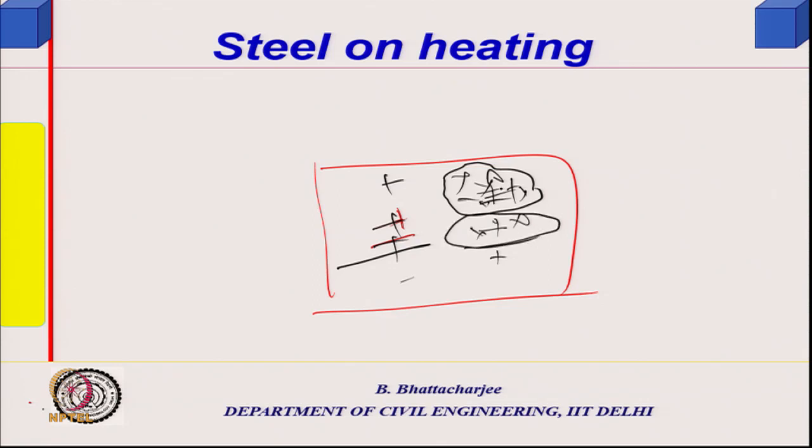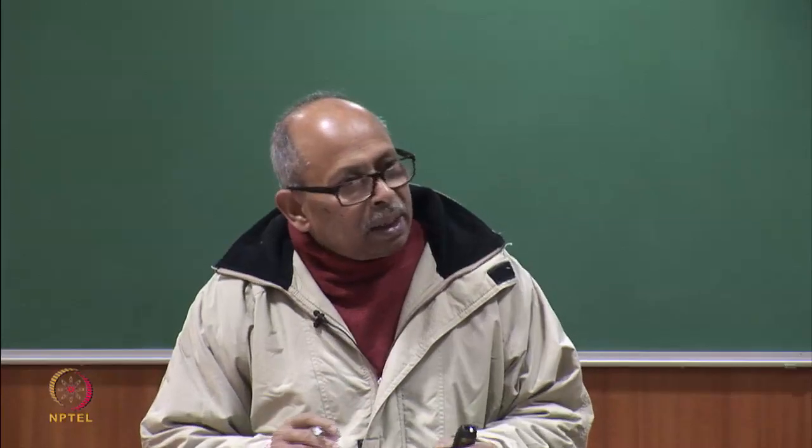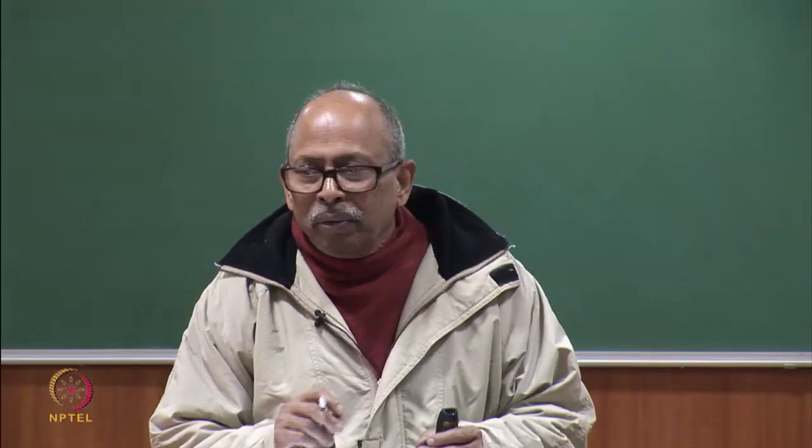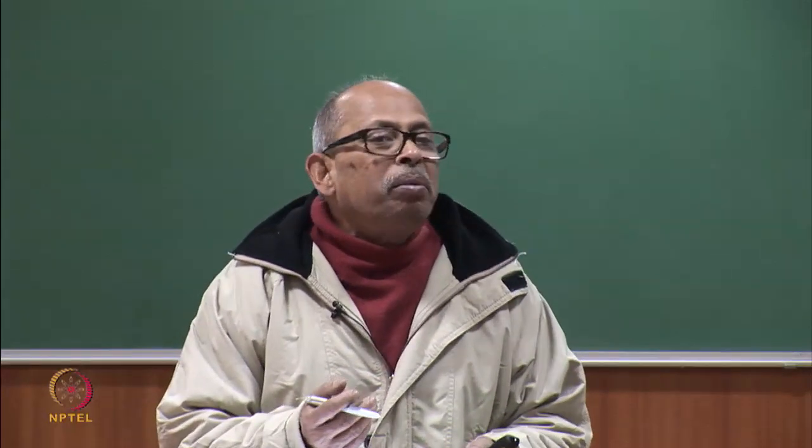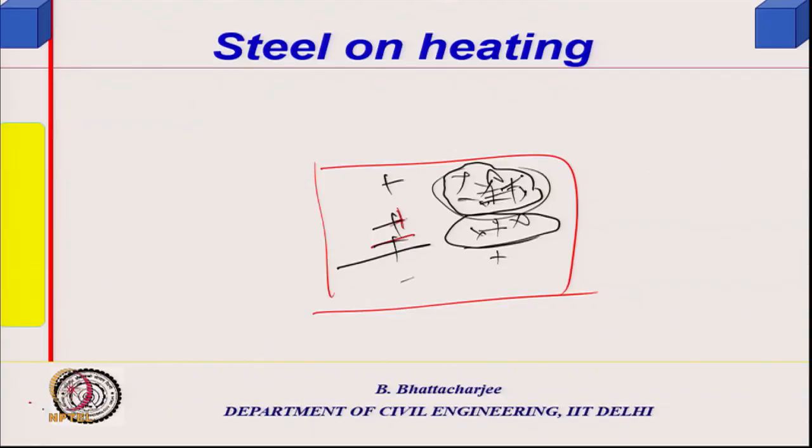Now, orientation of the crystal, this is called a grain. A grain is crystals all having similar orientation, and this is another grain. This grain also has a crystalline structure, atoms arranged in regular form, but their orientation could be different from this. So, finally, it all gets filled in. So, you will have a number of grains attached to each other with their boundaries, right.